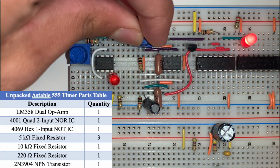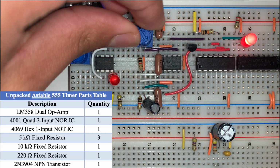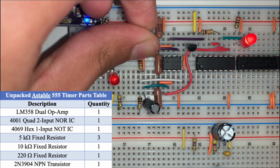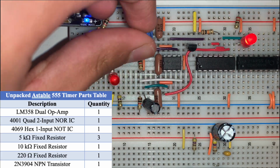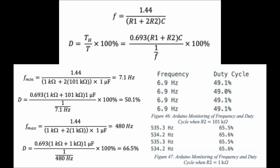The comparator outputs drive an SR latch built from NOR gates, which controls the NPN transistor to discharge the timing capacitor, and also drives a 4069 inverter to provide a buffered LED output. The clock signal frequency and duty cycle can be calculated.